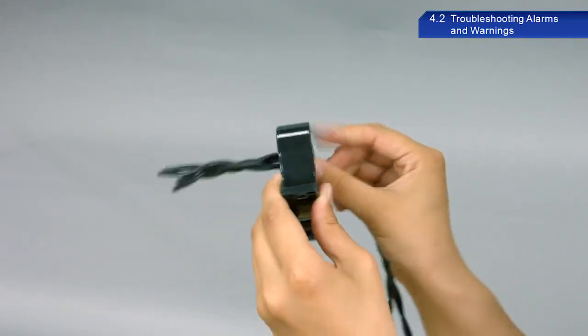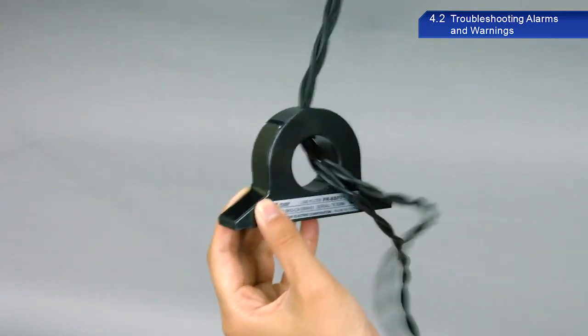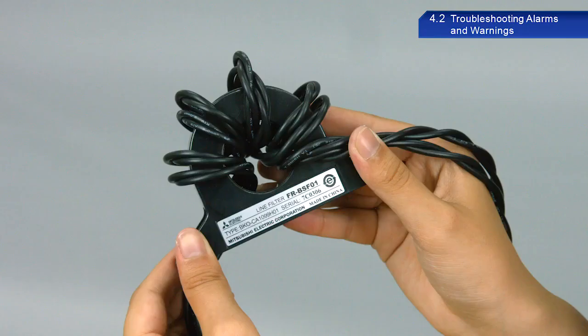All wires must pass through noise filters in the same direction and frequency. Using more filters for main circuit wiring increases the noise-reducing effect, but usually 4 filters are used. Placing filters close to the servo amplifier improves the noise-reducing effect.